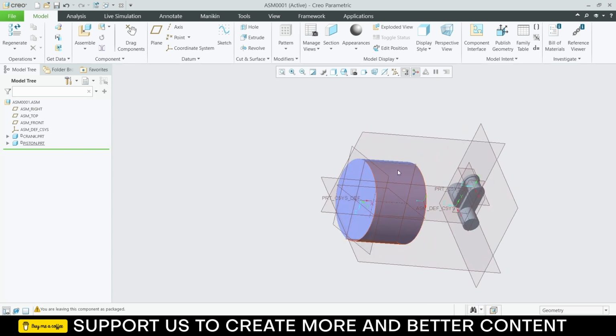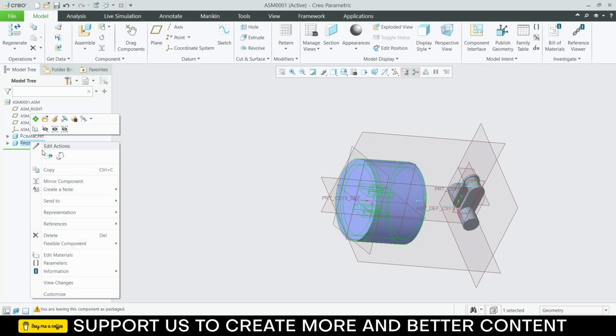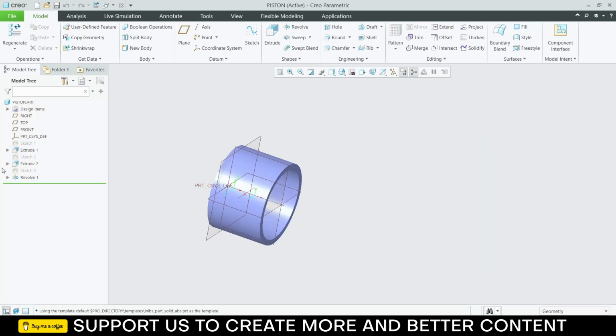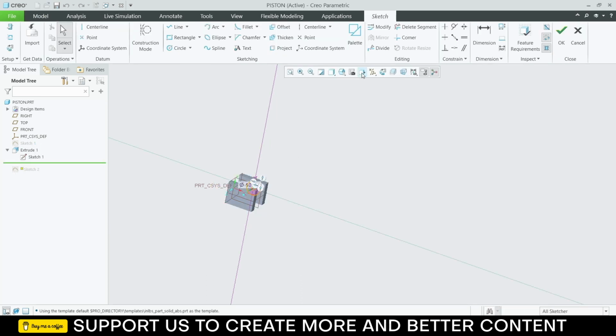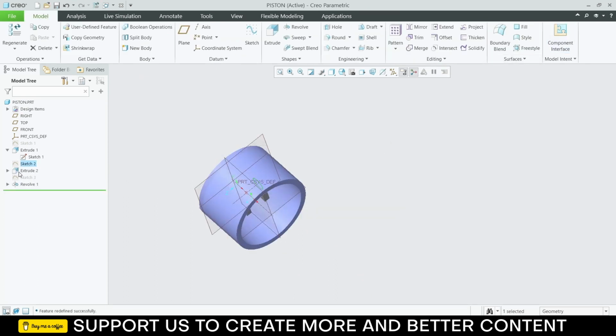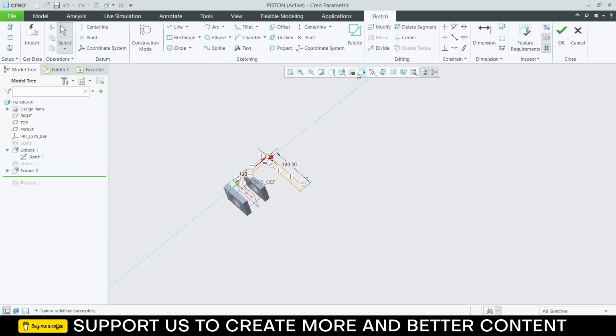So I will right click on it. Click on open folder. I have to change this one. Click on this dimensions. Click on normal to this. Okay, this is extrude cut, so I don't have to worry about it. I think this is the last one. Yeah, the revolve one. Edit dimensions and normal to the screen.